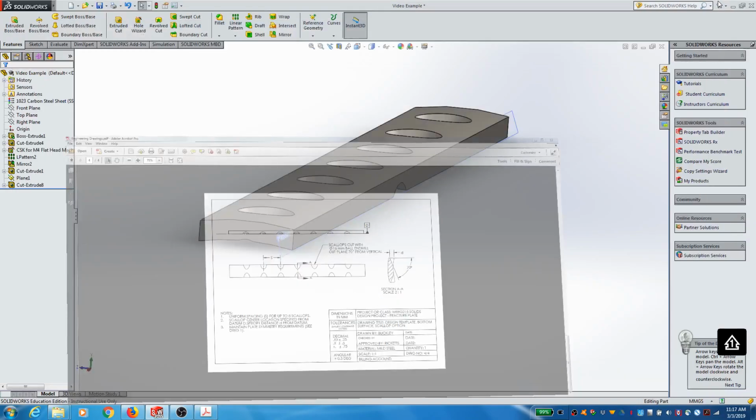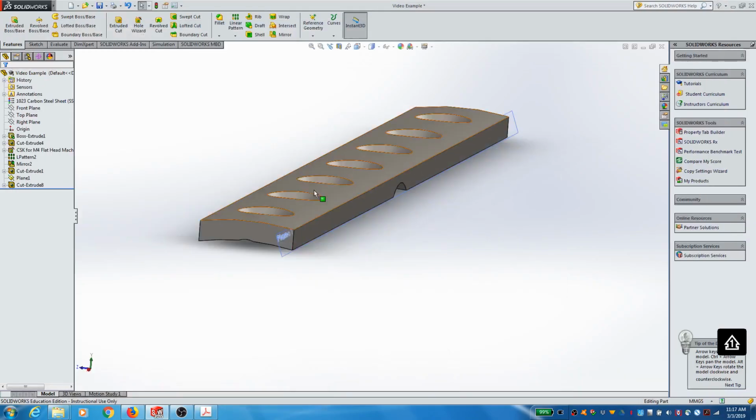So let me show you how you set up your model in SolidWorks. First, I would definitely do the rollback again like we did before. But the actual operation that you're going to wind up performing and then rolling forward looks something like this. First thing you need to do is set up a plane. This is an offset plane, but we're doing it in a specific way.